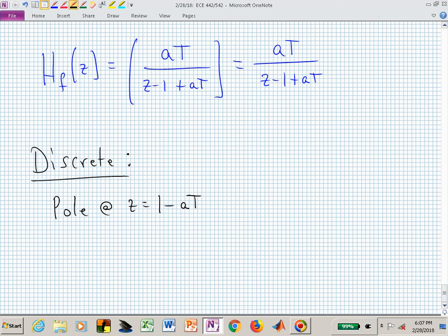Does that seem okay? Where is that pole? Is it real? It better be, since it's first order. Hopefully we've stayed on the real line. And where are we? Well, we're just a smidgen inside the unit circle from 1. z equal to 1 is our DC point in the complex z-plane, like s equals 0 is the DC point in the s domain.